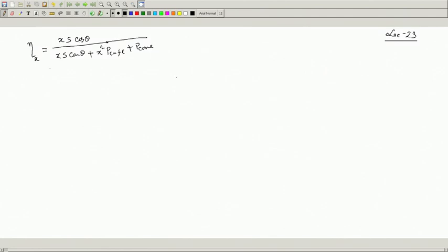And we found that the efficiency curve will be like this. This is some efficiency curve, and I must attach to each curve the power factor, cos theta equal to say 0.8. I showed last time that for a given kVA, this axis is x, the degree of loading, and this is your efficiency, and this is the value of x at which maximum efficiency occurs, P core by P copper full load, under the square root.